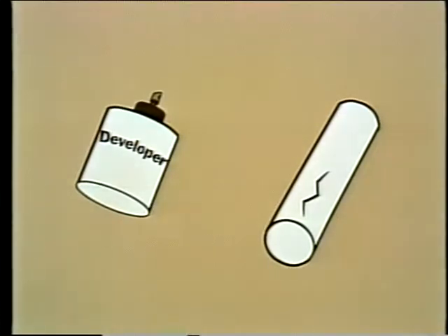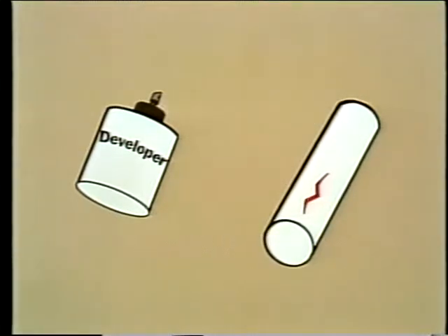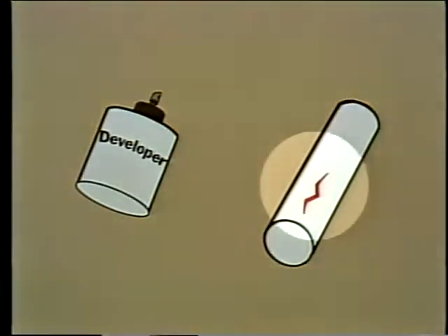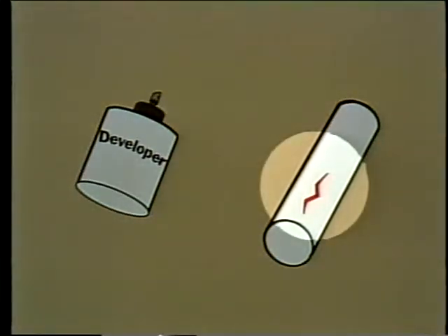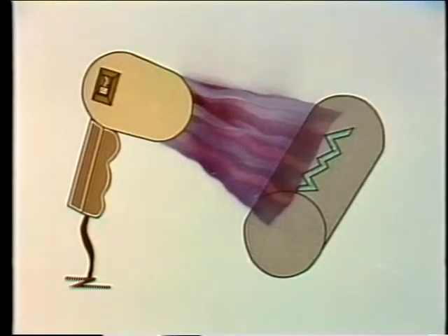After the excess dye is removed and the solvent is dried up, a developer is sprayed on the part. The developer is a very fine talcum powder that draws the dye out of the cracks, and it shows up in the developer. The indication not only shows the location of the crack, but also gives an idea of the shape and size of the defect. When a visible dye is used, the indication shows up immediately. With a fluorescent dye, a black light is used to make the indication of a flaw glow green.